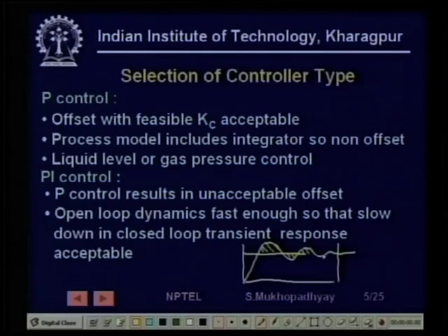Obviously you will find that they are acceptable when, see, every time there is a set point change, such an oscillation will actually result. It will die down, and then from then on, the loop will exactly achieve 0 steady state error.